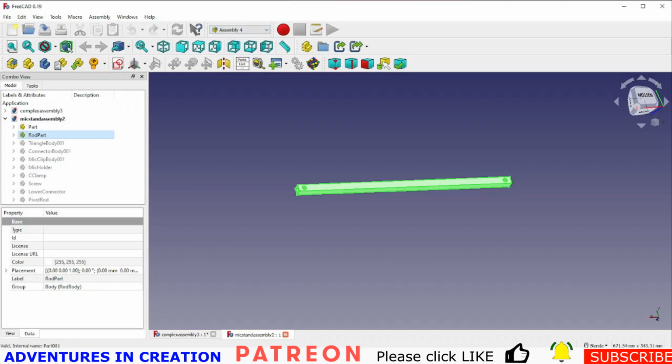So now I'm in Assembly 4, I have my rod part, and what I'm going to do is create an LCS on either end for the holes, because I want to assemble it by these holes. So we're going to do that now. Let me just make sure I'm in my rod body. Yeah, I don't have any other spurious